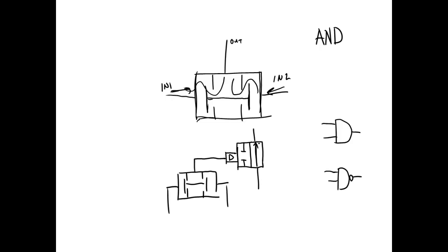So if I call this A, and I call this B, and I call this Z, then if I had pressure on A, I wouldn't get anything out of 2, right? You understand? And it would be over in the right position, so we'd have fluid flow to our actuator. If I put an input on B, then I'd have fluid flow. If I didn't put an input on A or B, then it was still center, and I'd get output, right? You understand that? If I put it on both A and B, then we have flow out of 2, or Z, that would push that valve over and stop it.